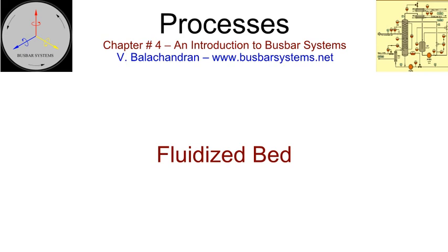It is preferable to cool the bus bars inside the oven to room temperature. This method of application is cost-effective and high on productivity. In a more advanced version of the process, electrically charged bus bars are introduced in a chamber containing a cloud of epoxy powder. This ensures better adhesion and uniformity.